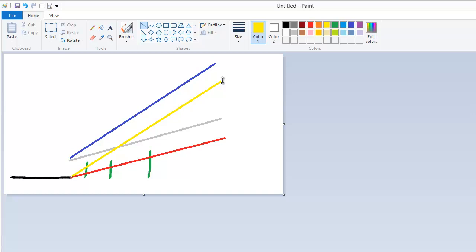and the point at which it crosses the gray line depends largely on the steepness of the climb gradient. The higher or the steeper the climb gradient, the closer that point where they cross is to the end of the runway. So in this example, the closest in obstacle is a factor for 135 clearance. It needs to be dealt with. The second obstacle out is potentially a factor because it is within the range of obstacles that are a factor, and the third obstacle is just not a factor.